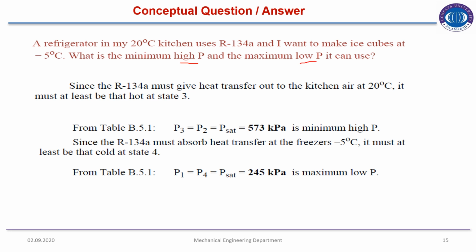So you know that the high pressure is provided in the compressor and low pressure is provided in the evaporator. Since R134a must give heat transfer out to the kitchen air at 20 degrees centigrade, it must be at least that hot at state 3.